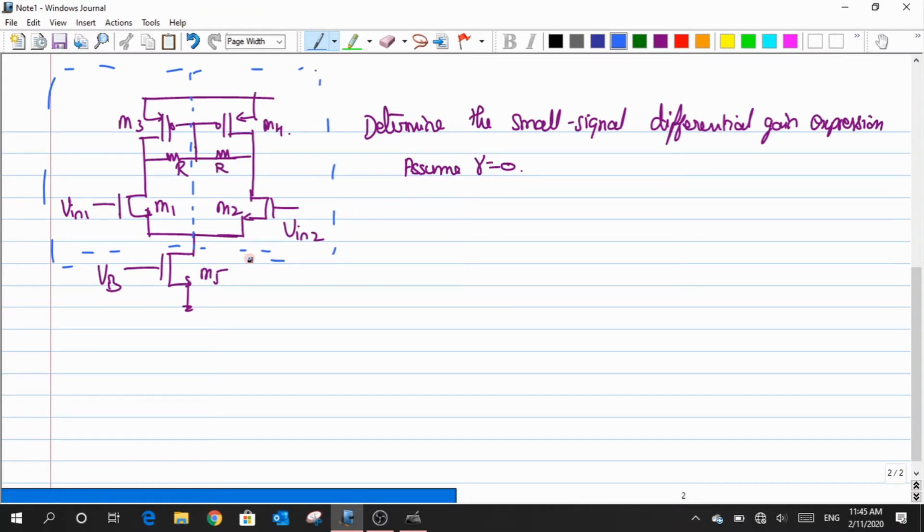So due to which the circuit is symmetric, and now since we are asking about a differential gain, the type of input that I am going to feed is going to be an antisymmetrical input. So what happens to this node when I apply this antisymmetrical input? Yeah, this node would be driven to the ground. So I will have the M1 and M2 source terminals connected to the ground whenever I apply antisymmetrical inputs. So now it is enough for us to take only one part of the circuit to analyze the entire gain, right? For this circuit, the resulting circuit that I would get would be something like this.